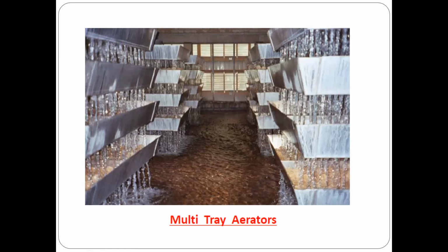So these are the things we have to observe. Whenever we are trickling down water, atmospheric oxygen automatically gets mixed, and due to perforation, whatever objectionable gases are present are also removed, and our purpose is solved. Water trickles down from one bed to another. You can see water percolates from the first tray to the second, second to third, third to fourth, and it is collected finally at the bottom collection pan.